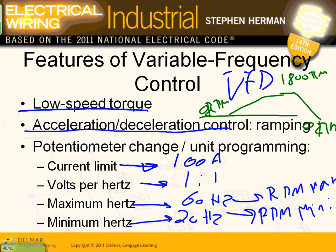So is the voltage coming from the voltage kicking back from the motor? No, this is all through the drive. All this is controlling the drive. When you push the button to turn the motor off, inside the drive says now we have to start the sequence of turning off. So it starts reducing the voltage slowly within 10 seconds.